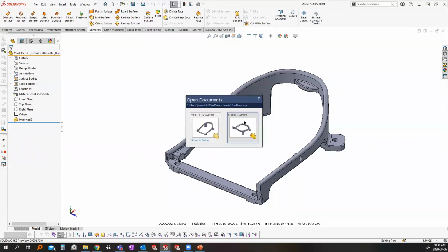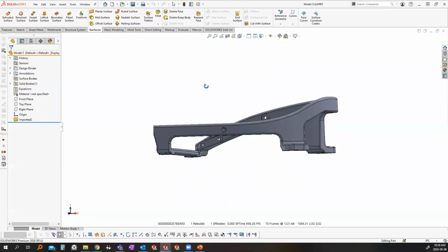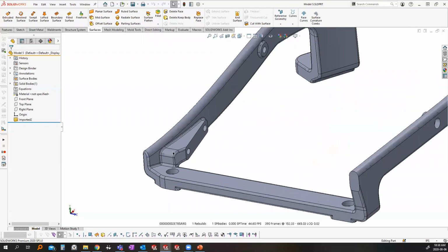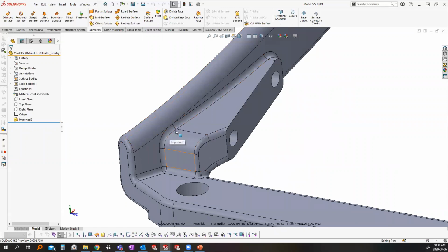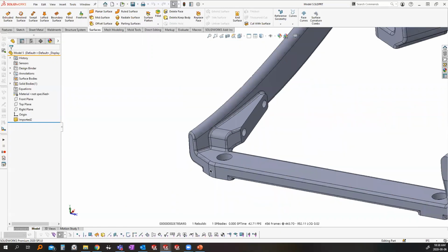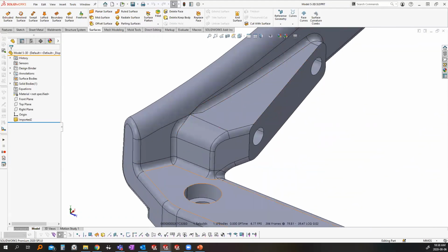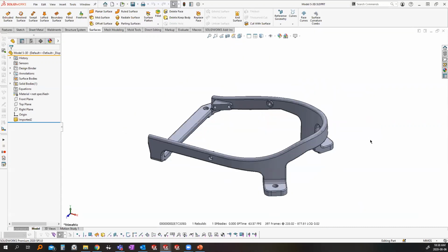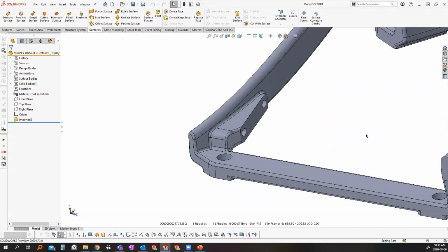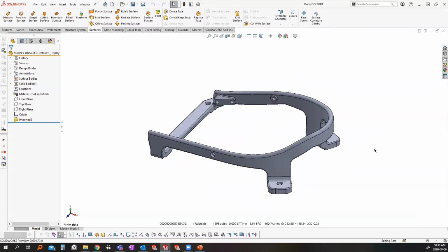You can see because it's essentially two different engines, if I'm looking close in this corner, I have fairly nice fillets here, and the exact same model translated through a different engine, I have not so nice. So this is why, again, I recommend trying out both and comparing.